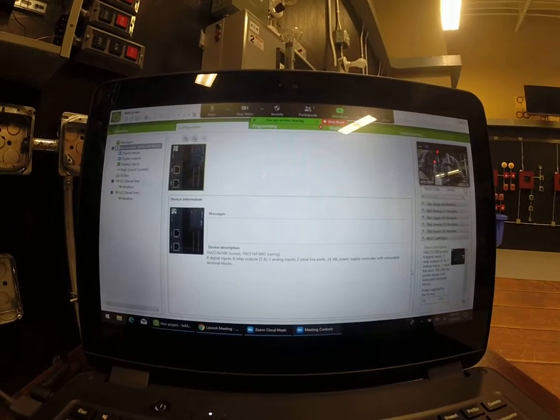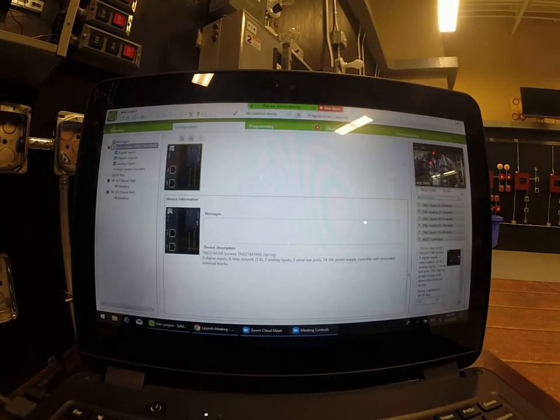What you're actually seeing here is the first of many videos of how to build a program, and in this instance this is the first motor control circuit that we did, which is a momentary start button that then feeds a coil. There's no holding circuit involved, it's just being able to convert the motor control circuit into a logic circuit so the PLC can see it.